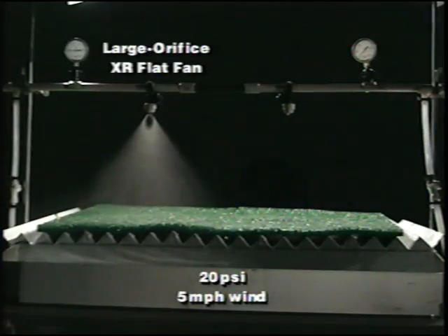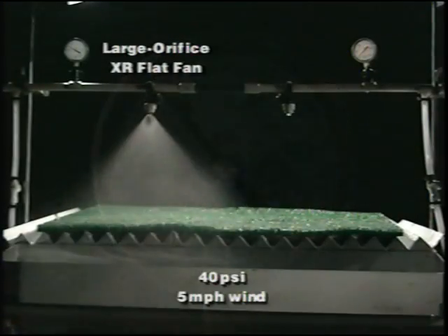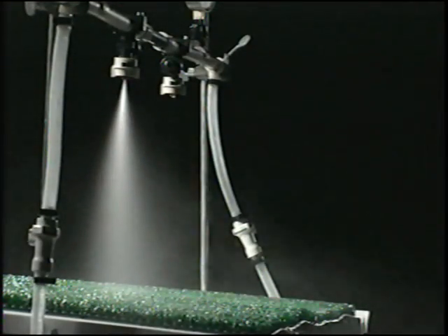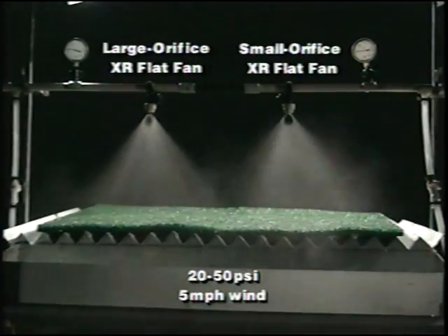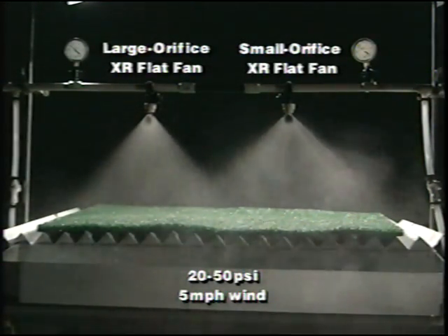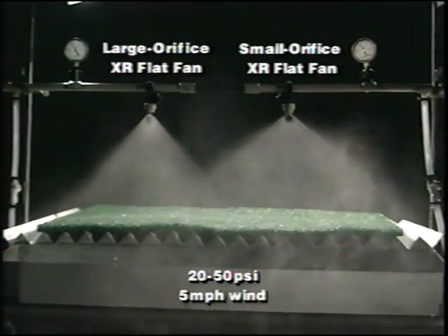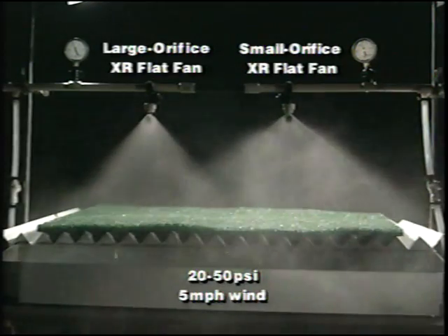For example, under identical 5-mile-per-hour wind conditions, watch the performance of this large orifice extended range flat fan nozzle under varying spray pressures. Now, comparing the large orifice extended range flat fan side by side with its small orifice counterpart, we can see a significant difference in physical drift.